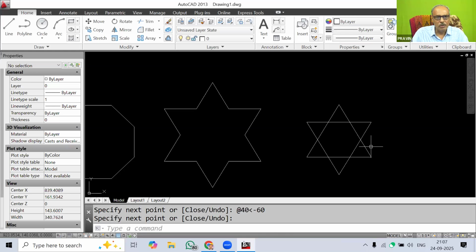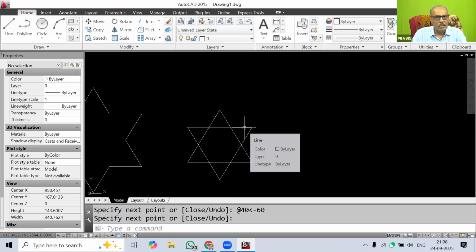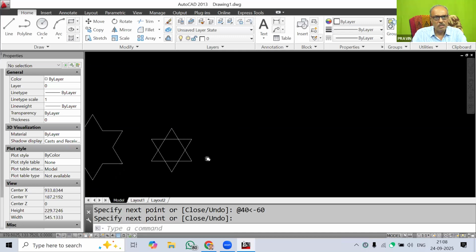So this is the magic of relative polar coordinates. So this is required. Now this is also useful in our building drawing. On the earlier day I have also shown how to draw the plot size using these coordinates. So that is also one of the important things. So I will again just repeat that part. Whenever I want to draw a plot size, what is required?